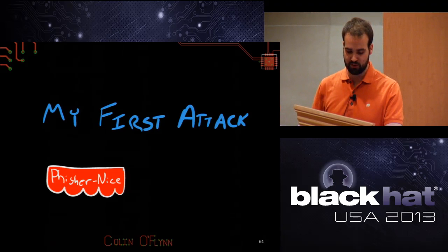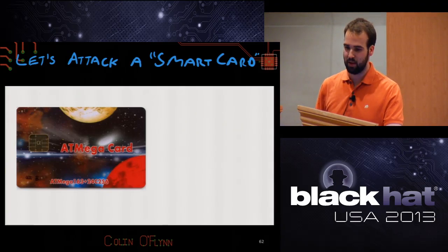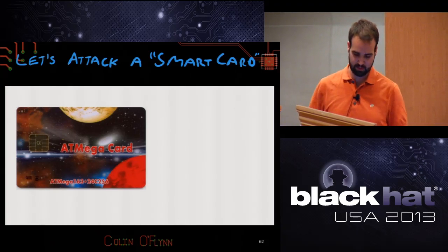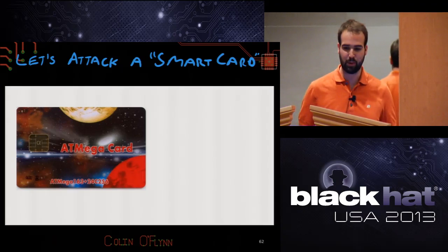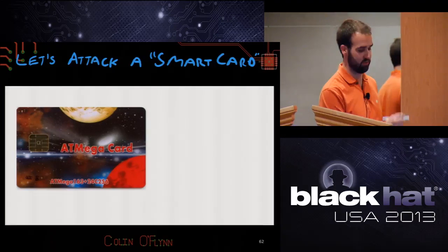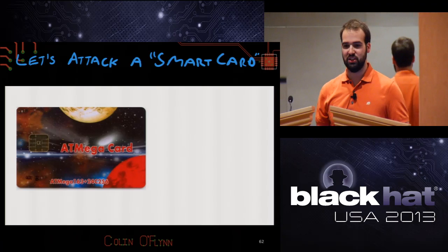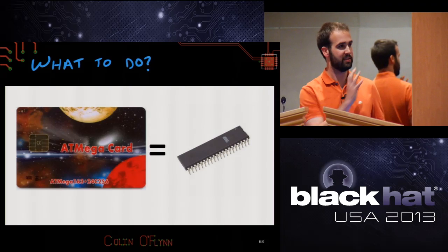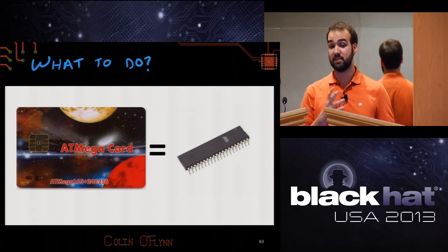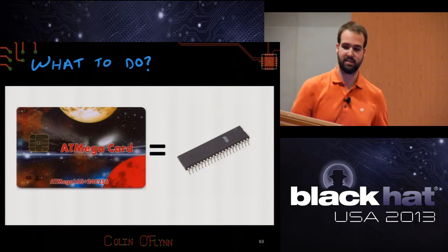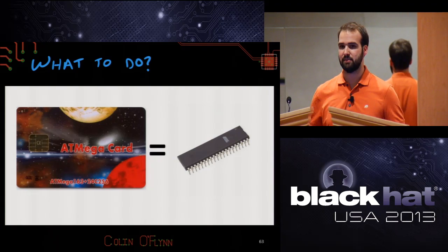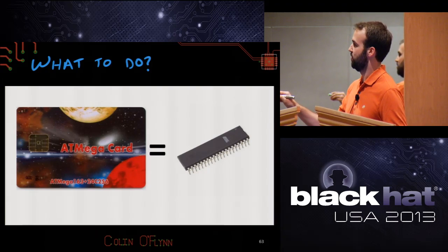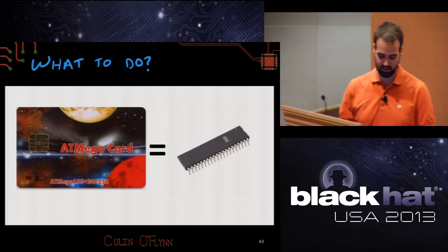So what would your first attack look like? And this is what I'll demonstrate after. You might say, well, I've seen demos with this stuff and they attack a smart card. That's cool. Smart cards are great to attack. The problem is they'll frequently use these cards, these ATmega cards or Funcards. And these cards are cheats because they are a regular microcontroller that happens to be in a smart card form factor. Nothing about this is special. In fact, you're doing a disservice by using these ATmega cards because they use an old microcontroller that has much larger power signatures because it's a larger geometry. You can buy a recent microcontroller and just program it yourself and you save yourself that hassle.